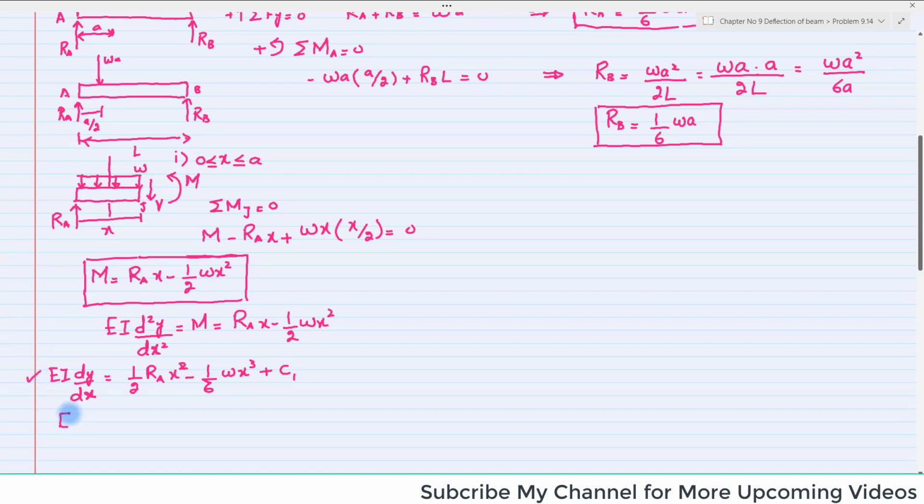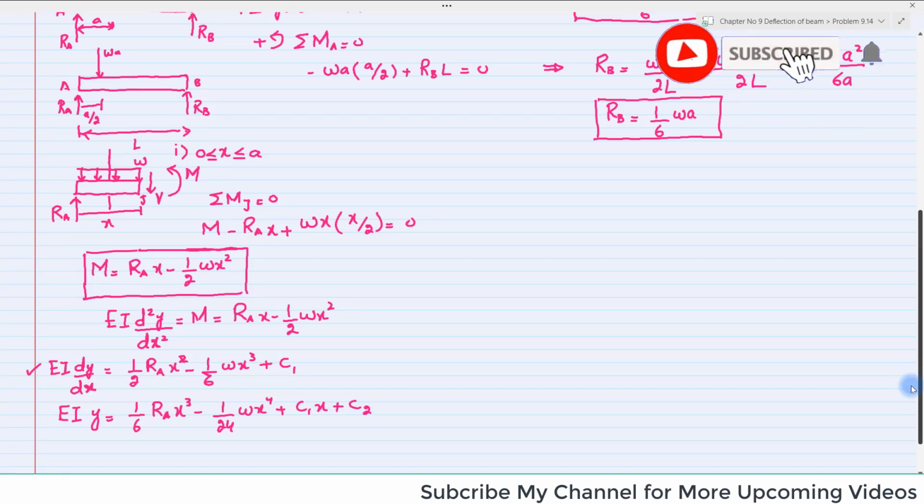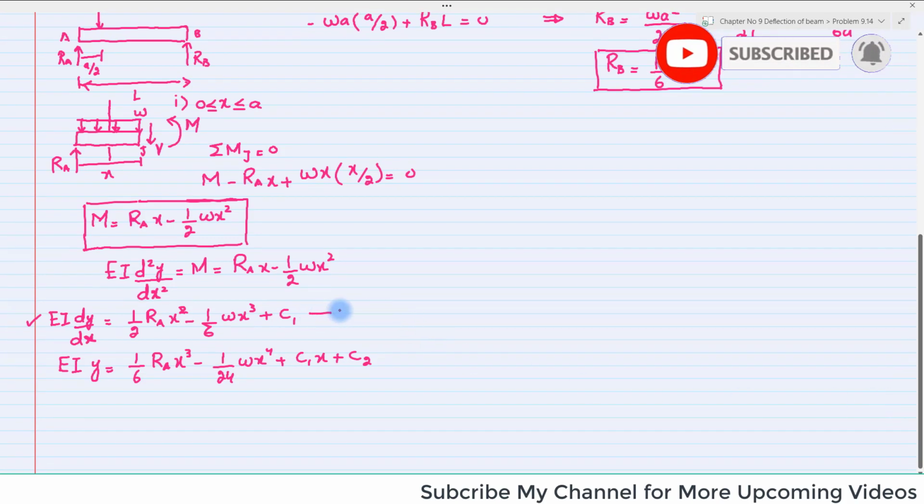So we will have EI y equal to 1 over 6 RA x cube minus 1 over 24 W x to the power 4 plus C1 x plus C2. Clear? Now we will apply boundary conditions. Let this be equation number 1 and this be equation number 2.